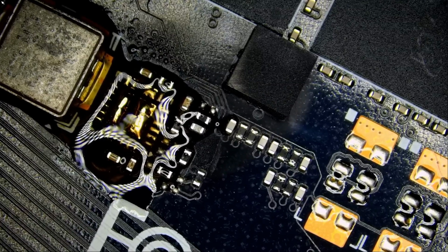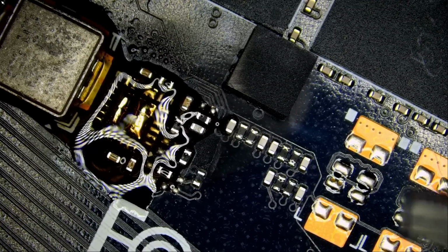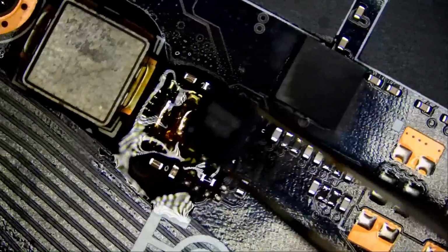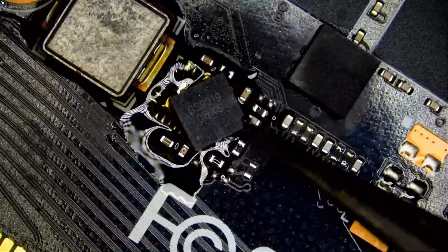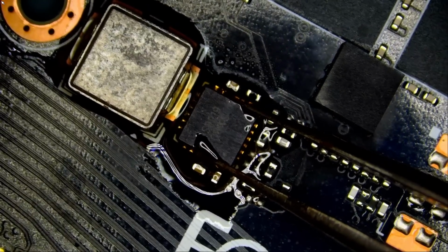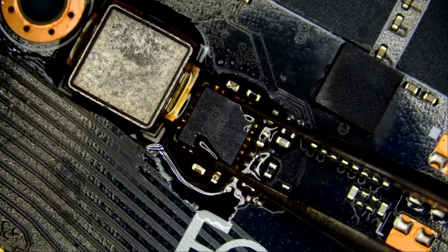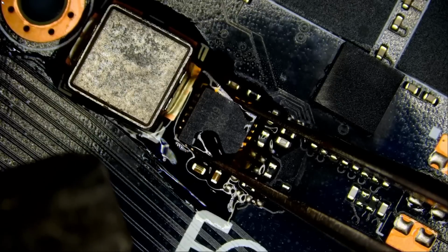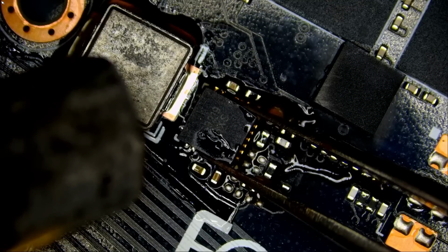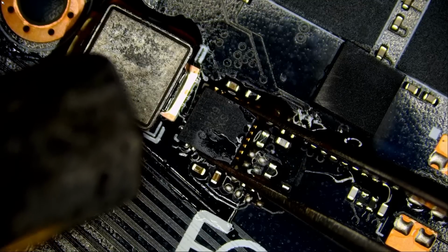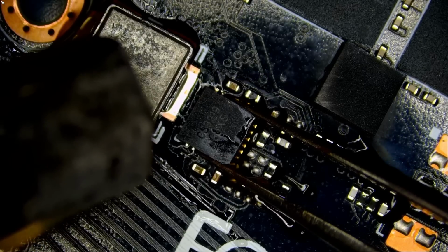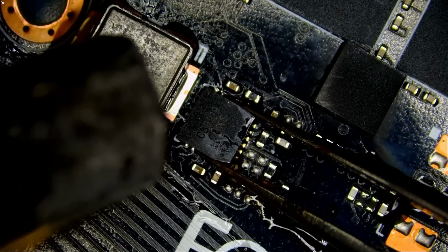The right amount of solder is not really a concern for me. The more solder, the better. If it squeezes out, we clean it. I mean, how awkward is it to first apply solder on the wick, make sure the wick sucks all the solder, then use the wick and hot air station, and then brush that wick on the board, possibly knocking off components on the board because of hot air.